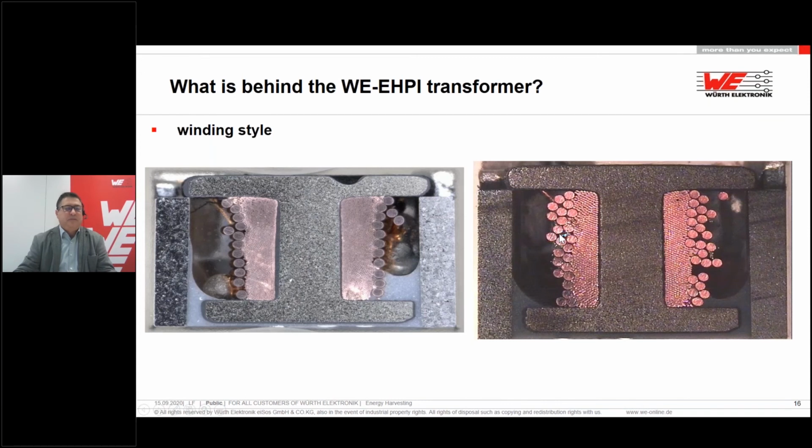How did we make them? Well, it's not a big philosophy. You can see here the mechanical cut on both. You have a bobbin core. You have here 1 to 50 wires. You can see the primary 1 to 50, the secondary 1 to 100 here. You can see on the left picture, this is 1 to 100. For the 1 to 100 ratio, we use a wire thickness which is thinner than human hair, the thinnest wire which a winding machine can operate.